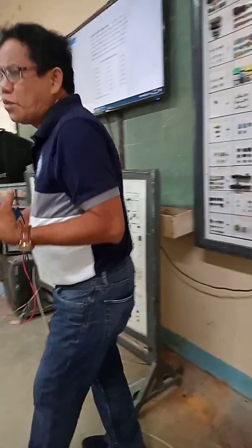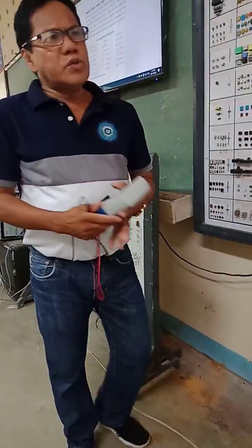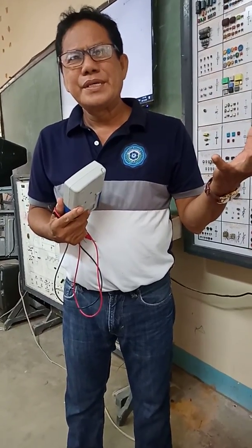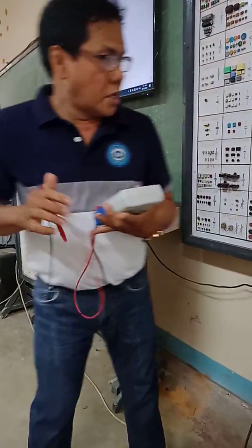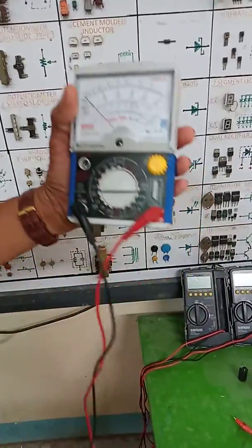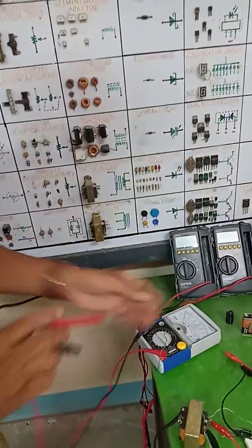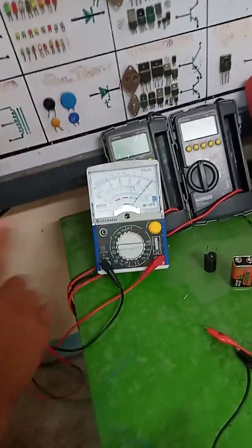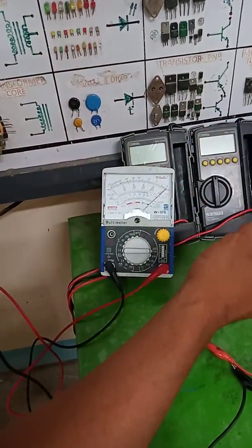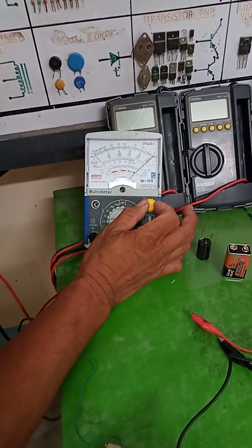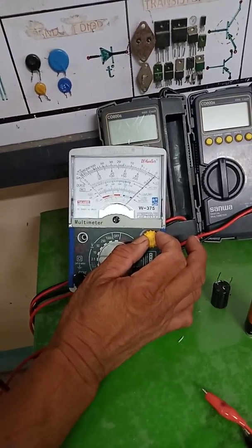And what are these insulators? Insulators are those materials which possess very high resistance and they don't allow the current to flow. So let us prove using the highest range to measure the resistance of these insulators. Short the two test rods. Usually the pointer deflects to the right. We will set it to 0 using the 0 ohm adjuster to have an accurate reading again. Plastic.